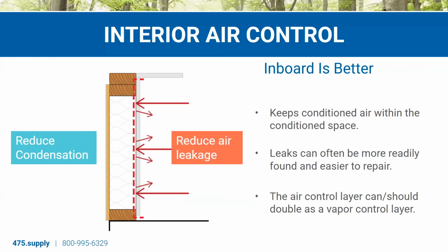So in northern climates, we're oftentimes including this interior air barrier. That is the Intello Plus or the Intello X membrane. The key thing that it's doing is just keeping your warm air within that conditioned space and not letting it move through that insulation where it would meet the backside of the sheathing during the winter. Now, with this type of interior air sealing, we don't necessarily need exterior insulation. We don't care what temperature that sheathing is getting because we're keeping our warm air within the conditioned space and not letting it meet that sheathing that could be getting cold.